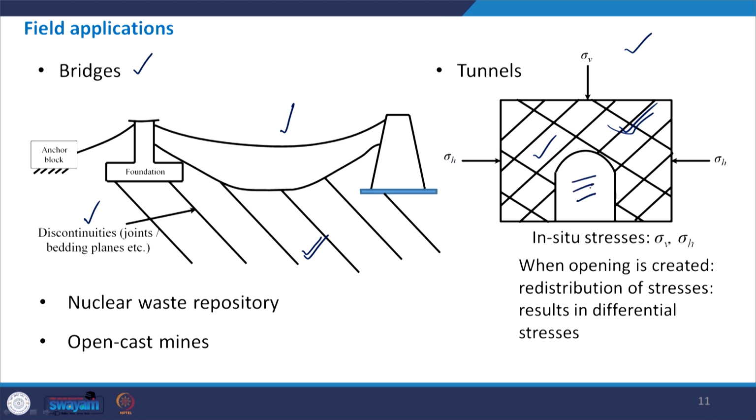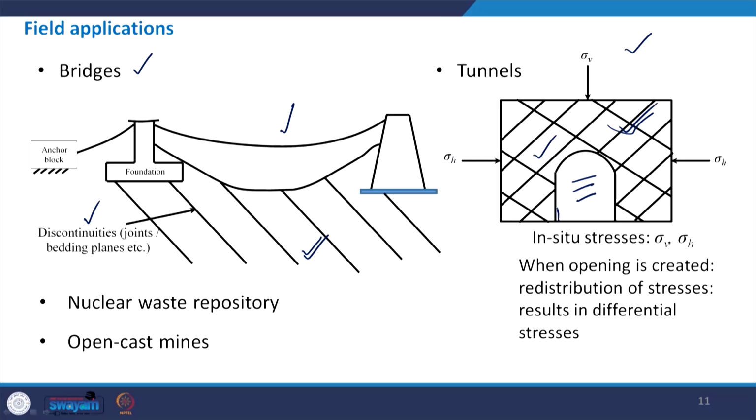So when the excavation is made, what happens to this boundary? This boundary becomes stress free. The moment it becomes a stress free boundary, there is going to be the redistribution of stresses, and this will result in the differential stresses.